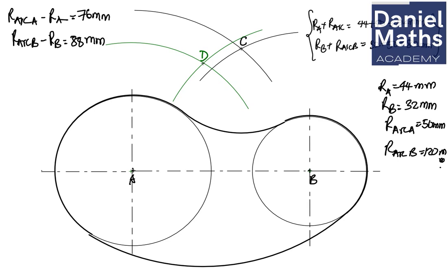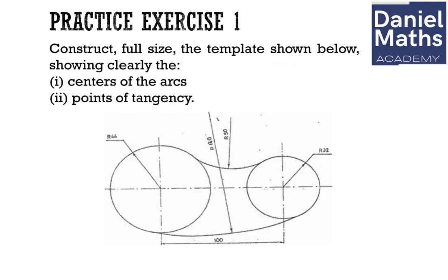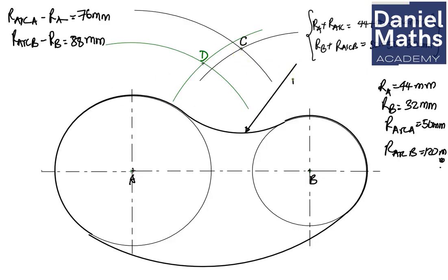All right, so I have to get my dimensioning done. So let me do this with my thick pen. All right, so I have my dimensions. That means I have this radius to be 50. Okay, so I'm going to bring this in from here. Sorry for that. So I have this to be 50 from this point. So let me use that to dimension this point. So this radius is radius 50.